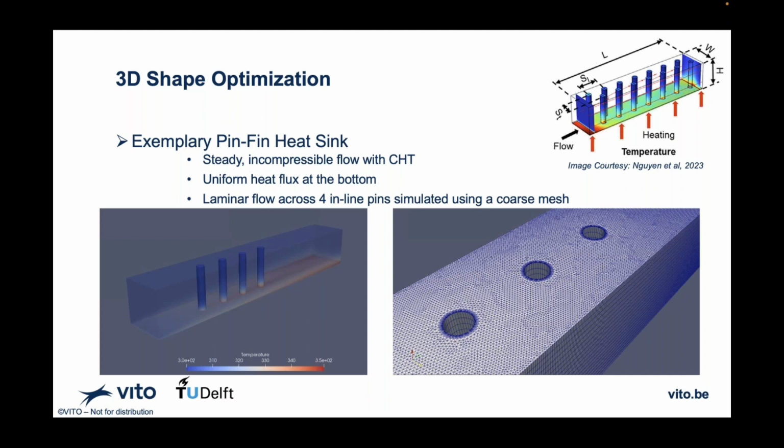And because you already have a CAD representation, I think what you can do in terms of mesh is have a remeshing or meshing workflow that just accepts a STEP file. Once you have a new CAD, you can run it through the workflow and it creates a mesh, because I suspect you're just using the SU2 deformation.